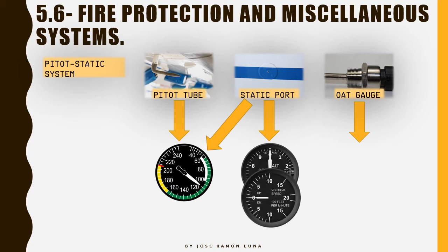And we also get the vertical speed, as we talked about in the instrumentation section. You can go again and take a look and maybe review some topics from that section. The vertical speed indicator is basically two aneroid capsules combined, two altimeters combined, which means that they are going to be comparing each other all the time to give you a reading of whether you are climbing or descending, and they're going to give you in feet per minute the vertical speed that you are achieving. And that's done only with static pressure.